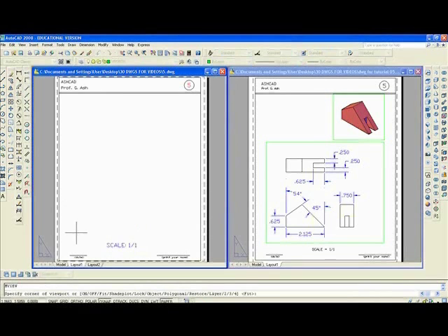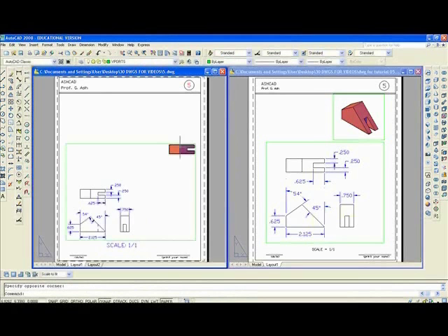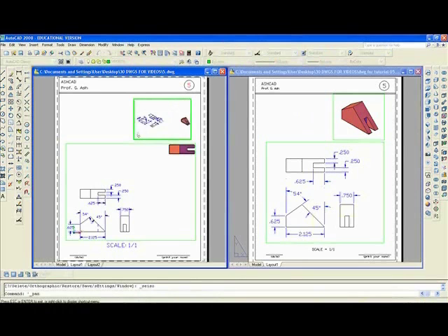MV, and make a big window like that. Enter. Make a smaller window like that. Double click inside the small one. Go to Southeast Isometric. Pan. Zoom with the window. Or zoom with real time and pan.